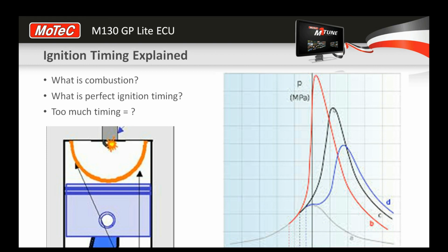What we're actually trying to achieve here is for peak cylinder pressure to occur at a particular location in the cycle. Generally that number is something like 17 degrees after top dead center. That's our ideal location. So if we keep advancing the ignition timing until we get peak cylinder pressure at 17 degrees after top dead center, then that ends up being our peak or maximum torque point.